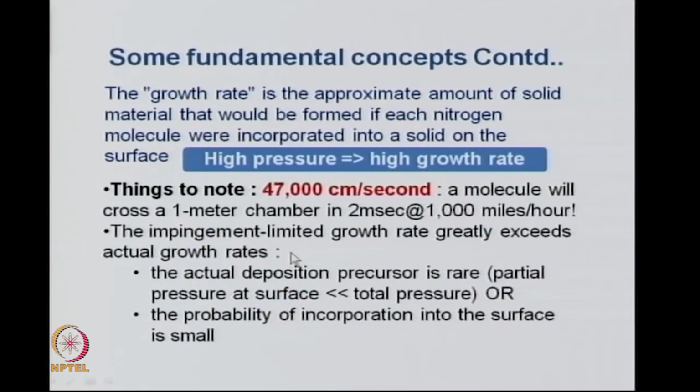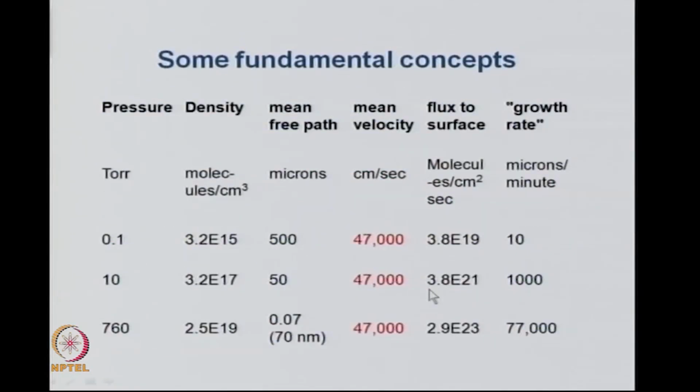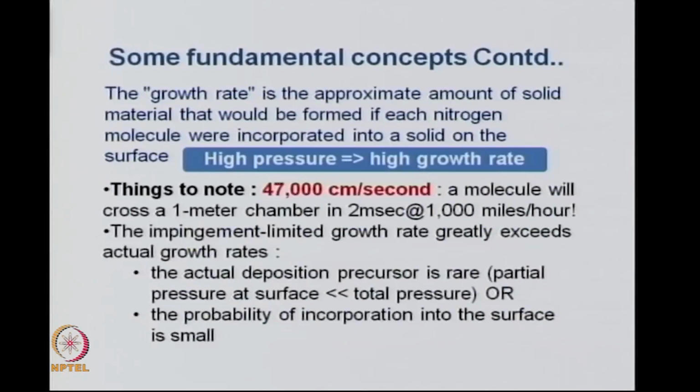So, this is the kind of speed of molecules that you are talking about when you are studying the impingement of gaseous molecules on the substrate or on the target. Now, the impingement limited growth greatly exceeds actual growth rates. That means, whatever we are calculating is much larger. What we are showing here is, say, 10 microns per minute. This is the calculated growth rate. In reality, this will be less in an actual experiment, and the reason is that the actual deposition